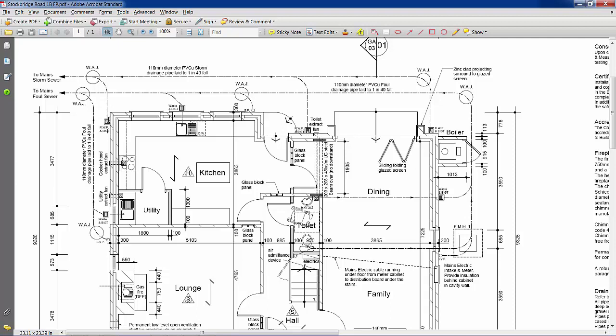So you would draw that circle and then have the top of the gully showing, which is a square usually, sometimes a rectangle, and the lines are indicating the grills on that. So that's maybe 200 by 200, something like that. And you would have a series of those around the dwelling to accommodate the rainwater pipes.